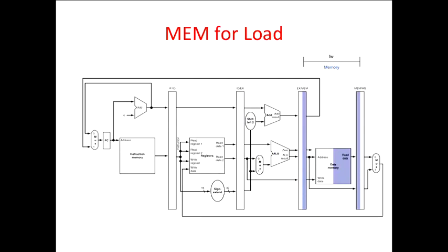Yep, Daniel? When you say it's a register, do you mean like it stores only 32 bits? Or, because I see a lot of inputs, how does it know? Yeah, good question. When we say register, it's a bit of a generic term. This is as many bits as you need to capture all those values. So this is a set of flip-flops that are clocked, and they capture all those signals coming in and delay them until the start of the next clock cycle, right?